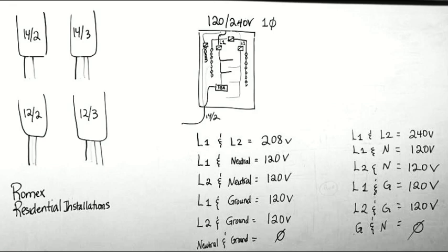And then you connect the vacuum cleaner. Sometimes people will say, oh, I just turned on the vacuum cleaner and the breaker tripped, and I don't know why. But they didn't know that on the other side of the wall, somebody had a heater on. That heater was on with 13 amps, your vacuum cleaner turned on with 8 amps, and your circuit was only 15 amps. So what did the breaker do? It turned off the circuit because too many amps were flowing and it was overheating the breaker, okay? So this is what happens when you wire a circuit in parallel. All of the amperage adds up, and our constant value is going to be the voltage, all right?